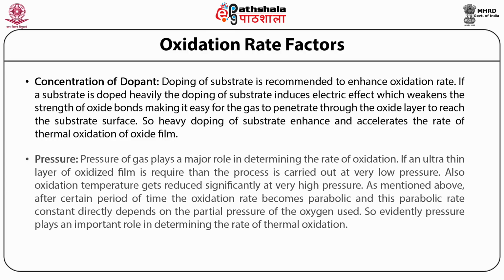Next is pressure. Pressure of the gas plays a major role in determining the rate of oxidation. If an ultra thin layer of oxidized film is required, then the process is carried out at a very low pressure. Also, oxidation temperature gets influenced significantly at a very high pressure.